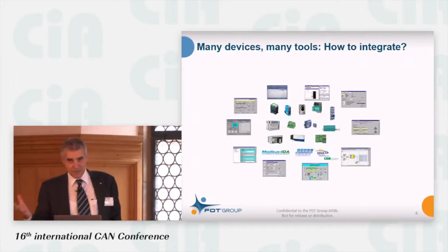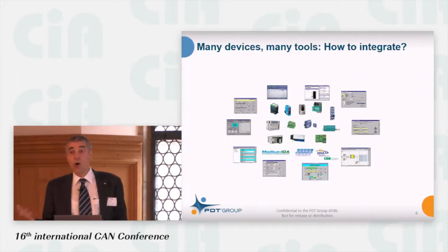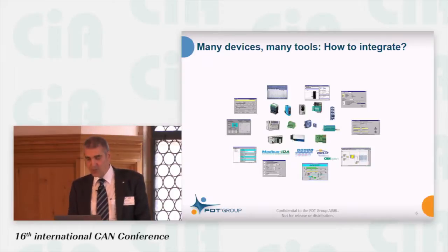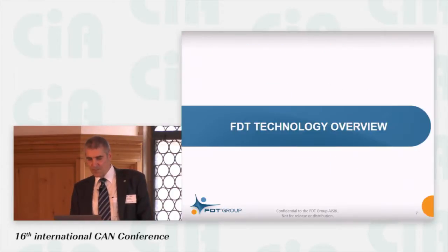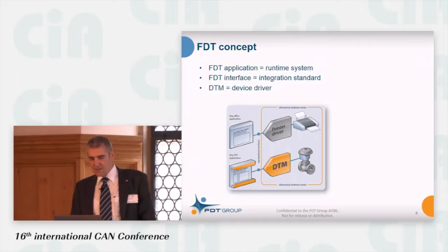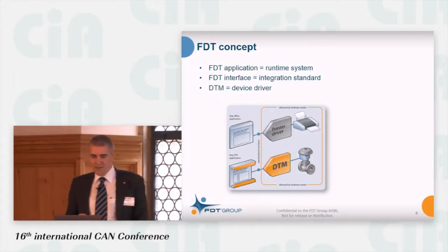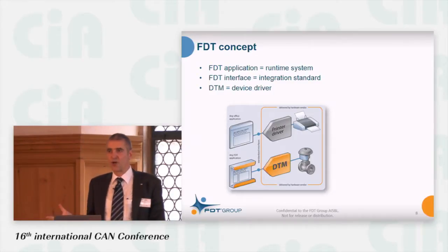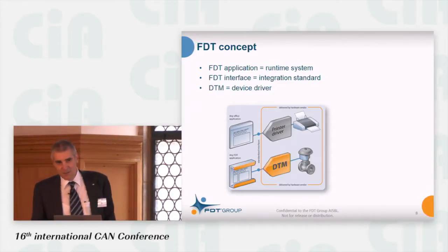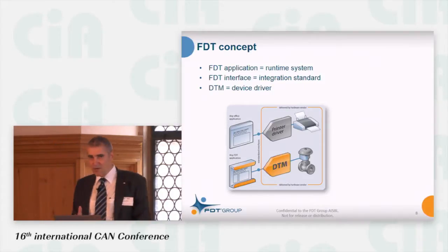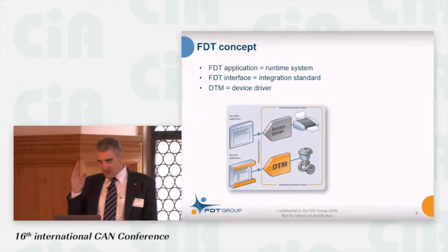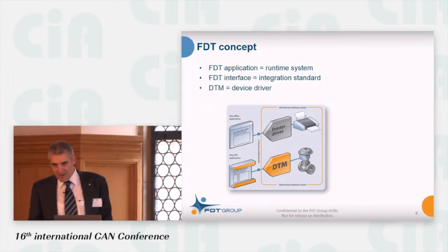So that means we have many devices, we have many tools, so how do we do this integration in one tool? So the FDT concept, we compare it, this is the similarity with a printer driver. You get a printer from a manufacturer, you install this printer driver in your system and it works because there is a standard interface for printers.